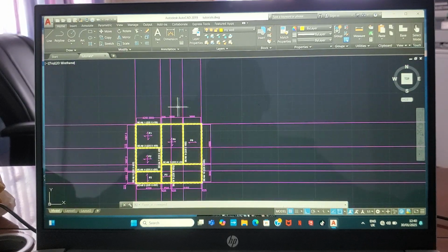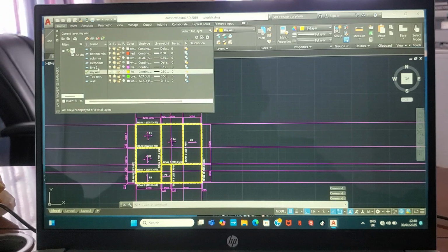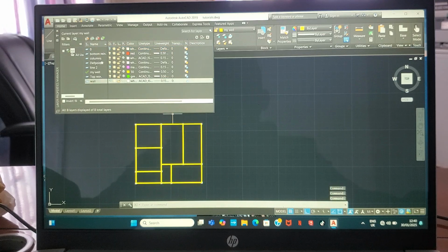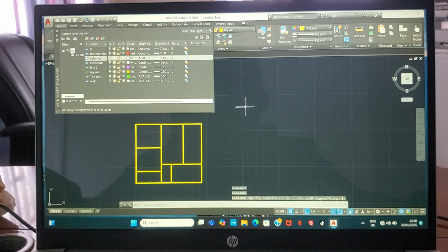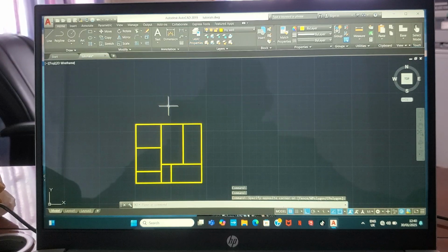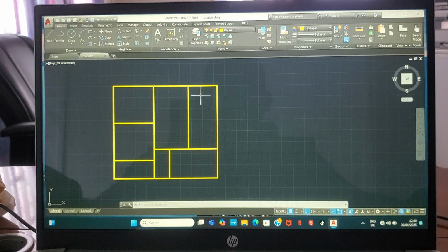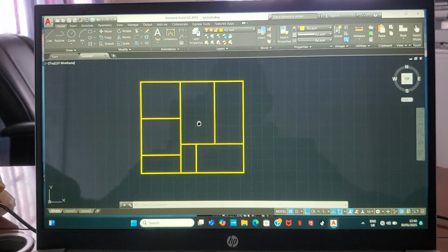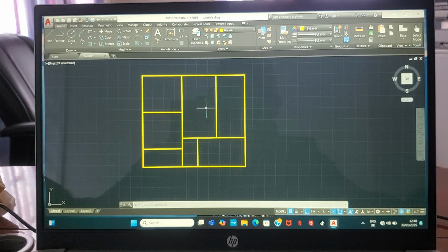Now what I need to do is go to my layer of the grid of my wall. You can see, turn off the wall, then turn off the column. So this is why AutoCAD is very interesting. You can actually turn off the lines that you don't need. You can see that all the panels are now represented with rectangles, just lines. This is what the software needs.